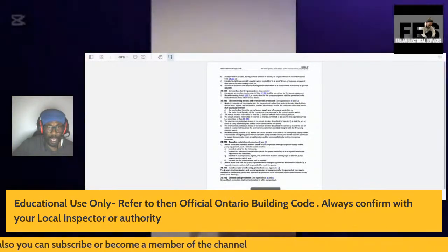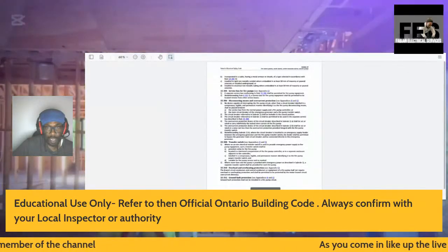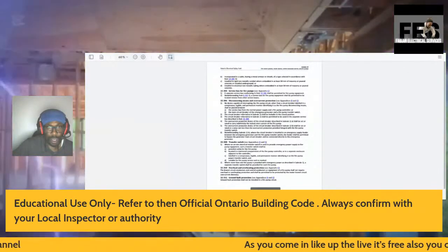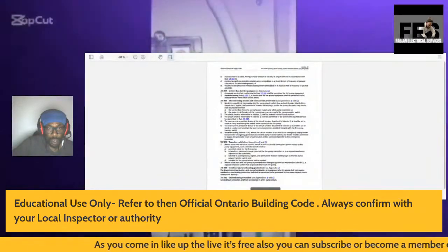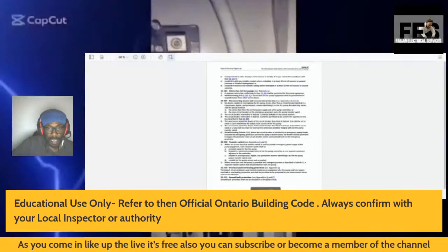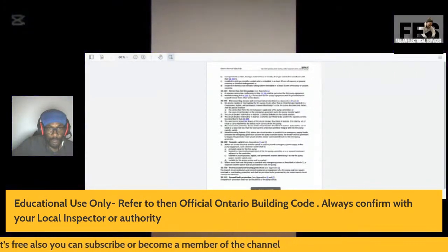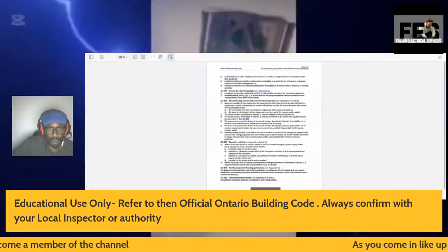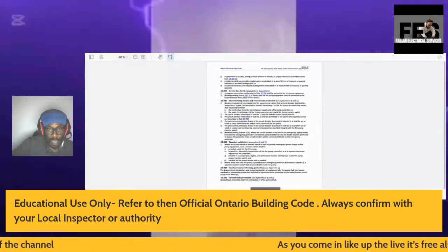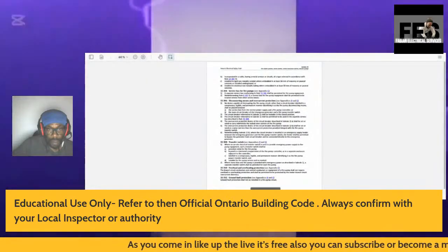Incorporated in the cable, having a metal armor or sheath of a type selected in accordance with Rule 12-102. Installing rigid non-metallic conduit where embedded in at least 50 millimeters of masonry or poured concrete, or installed underground, or installed in electrical non-metallic tubing where embedded in at least 50 millimeters of masonry or poured concrete.